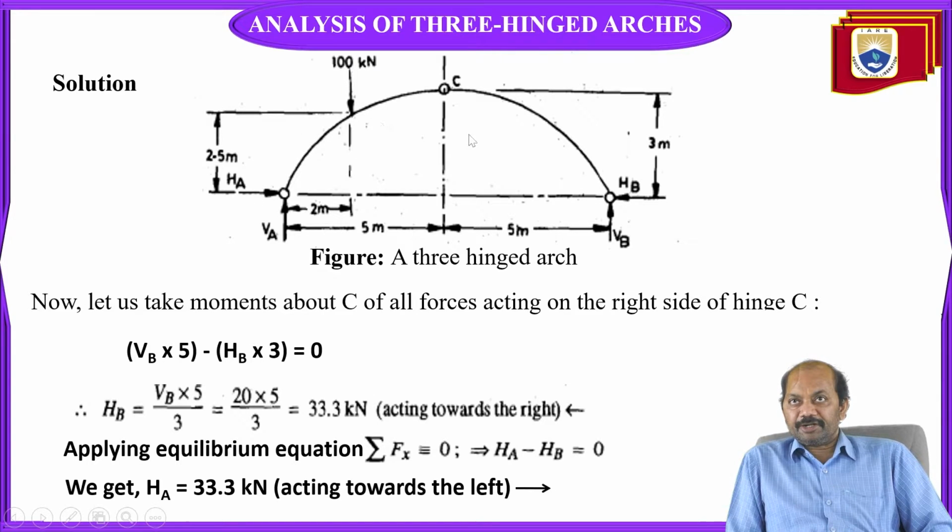Hinge is located at a point C. Remember, whenever a hinge comes in a structure, its bending moment will be 0. So, using that principle, we made it here 0.